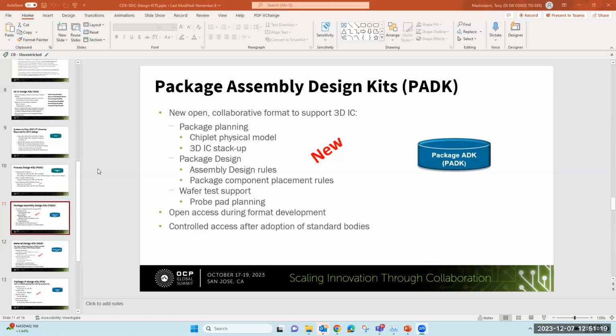So this is pretty straightforward for an interposer or a flip chip die. When you get into micro bumps, that's where people are putting in what are called sacrificial pads, where you sacrifice a few of those micro bumps and just drop in a pad, which is not used in packaging.